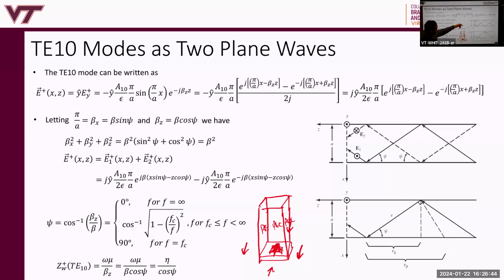All right, so then I could put a port on the end of this waveguide and send the TE10 mode down. It reflects off of the patch antenna and comes back up. I measure the reflected field, calculate an S11, and from there I can calculate the reflection phase or the reflection coefficient of this patch. The TE10 mode is not the only mode we can excite, but that's the one we would use. And then what's the incidence on this patch? Because whenever we do periodic boundaries, we assume a Floquet mode, a plane wave, coming in.